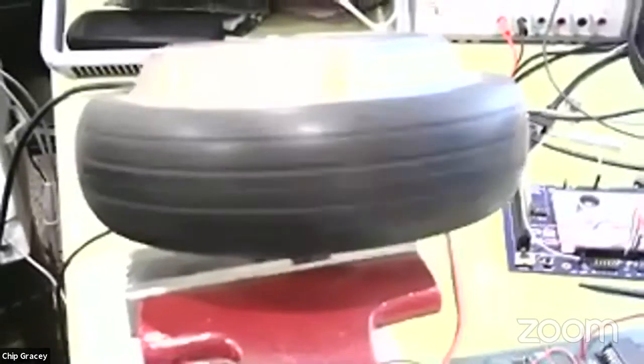Here's the funny thing. It's using full power PWM to drive, but because it's hitting at the proper 90 degrees offset, it just doesn't take much juice. It's not rigidly holding the motor as it turns it. It's just moving it to where it needs to go next. So now I'm at 20 volts and we're only at half an amp, but it's really cruising now.